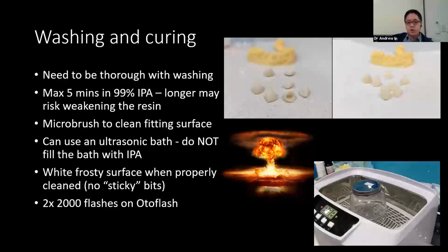It's much simpler for you to, as I've done here, put your stuff in a jar and fill that jar halfway or a third of the way with IPA, and then put that jar in an ultrasonic that's been filled with water. Much safer. You're not going to be wasting that much IPA, and yeah, that's the way to go in my opinion.